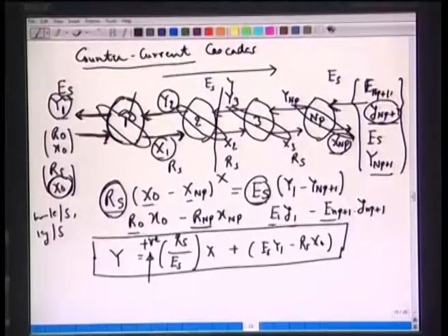So, what we noticed here, we have made a species balance for co-current, cross-current and countercurrent cascades, very similar to the previous case where we made a species balance for co-current continuous contact process and countercurrent continuous contact process. The overall material balance remains the same. We have negative slopes in case of co-current or cross-current, and we had a positive slope in case of countercurrent flow, the countercurrent continuous contact process or the countercurrent stage-wise processes. However, these are discrete: we have stage 1, stage 2, stage 3, whereas there we had one continuous column, which is a packed bed. Although we are getting similar mathematical expressions.